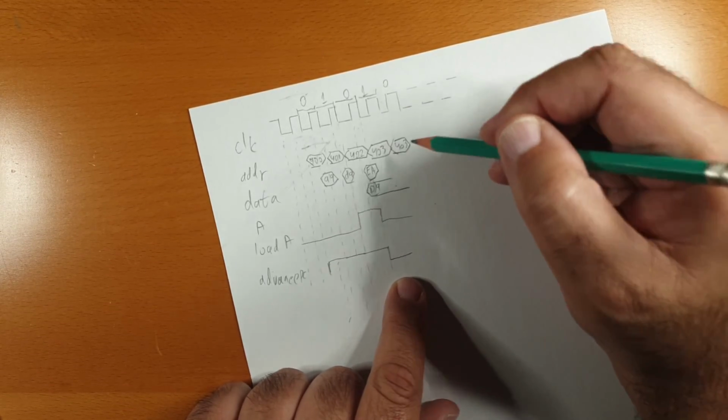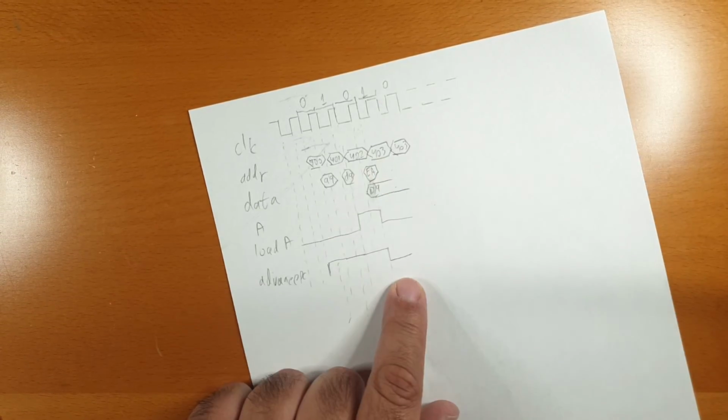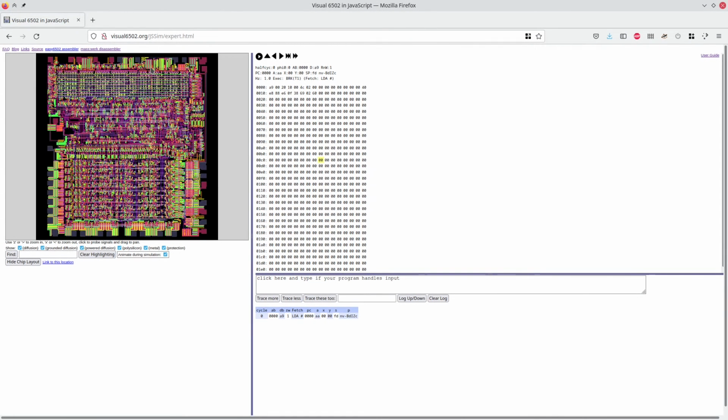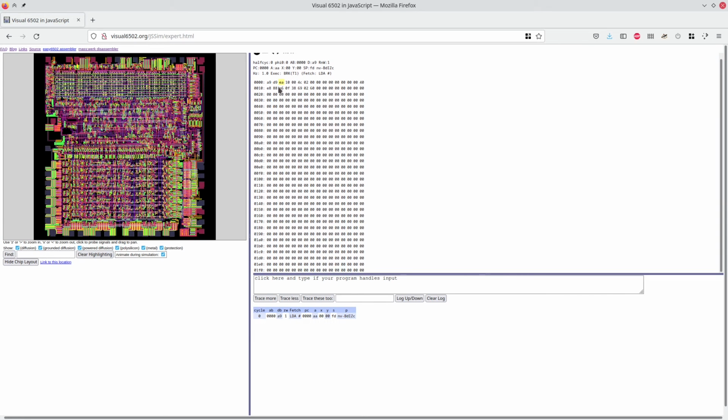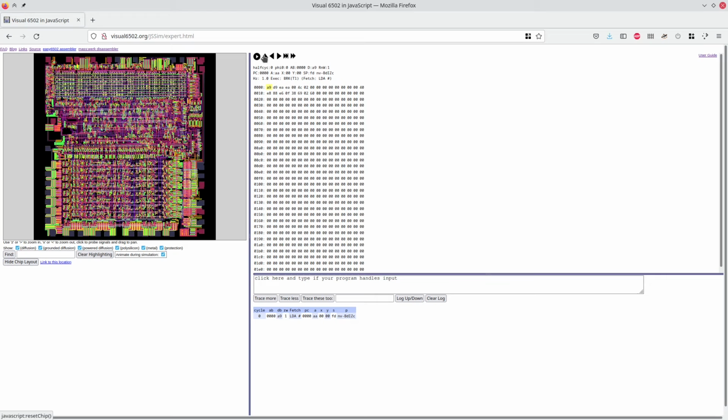And we actually see this in CPU execution. Here, let me show you. This website is called Visual 6502, and it simulates the MOS 6502 by actually simulating the individual transistors involved. Let's load the memory, A9, D9, and then of course EA, EA, which are the no operations. Click on the up button and the bus is updated. So, falling edge of the clock, the address bus says 0000, we're using a different address here. The data bus says A9, RW is 1, which means read, and for our benefit, it interprets it as load A immediate. Program counter is 00, and the A register is AA.